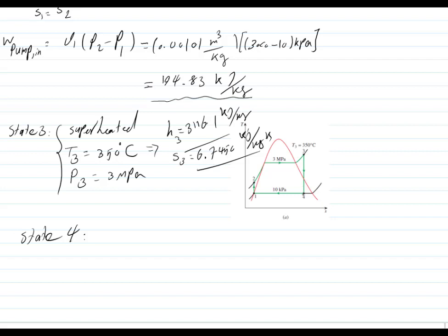If you notice, in state 4 we are in the mixture region. Here we have a steam which contains some moisture, but the information also which we have for this point is, first of all, S3 is equal to S4 here, as you can see. S3 and S4 are identical, and moreover, we know this is in the mixture region, so we can write this equation. If you remember, also we had this equation in the previous example.